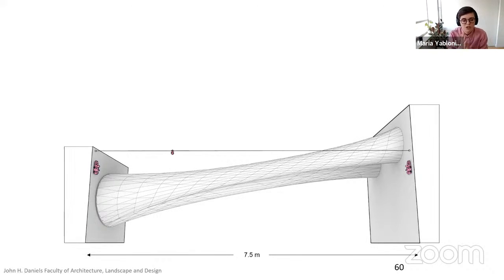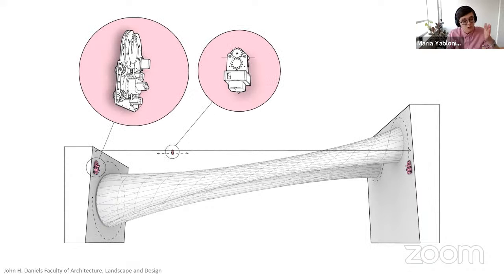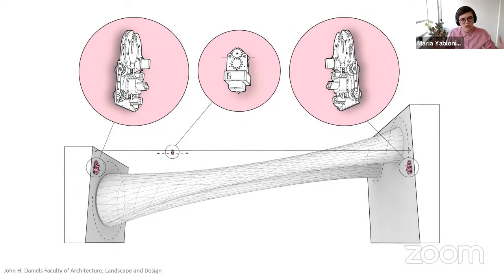In my work prior to this project, I had already been developing wall climbing robots that manipulate filament types of material in order to create tensile structures. But here, because the 2 walls are separate from each other, I had to think not only about the machine that can operate on the wall and anchor the filament to the wall or to pre-installed anchors, but I had to extend my taxonomy of robotic creatures. That's where I began to think about different types of robots working together to create a fabrication system that is still pretty simple in terms of degrees of freedom of each separate machine, but becomes quite complex and provides a really nice volumetric design space through this collaboration between multiple machines.